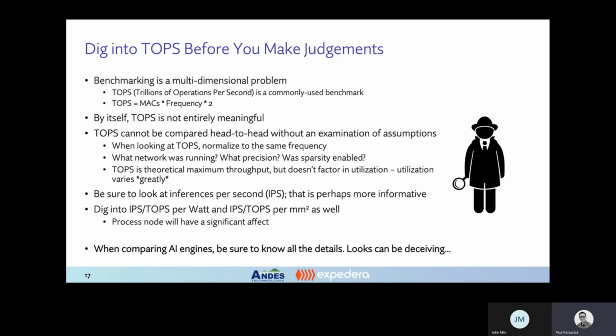As a system designer, as a chip designer, you really need to explore that utilization number and understand how it changes depending on the TOPS that you're at. Is the utilization consistent across the performance range of the product, or are you being given a utilization number that's specific to a sweet spot and has a significant roll-off as soon as you go away from that?